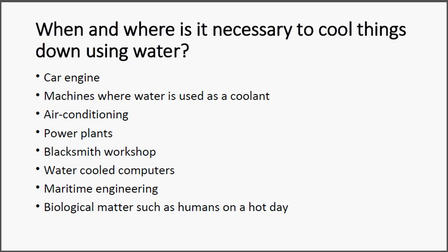And in a car engine, it's a little bit special as well. We don't want it too cold, but we don't want it too hot either. Water has a boiling point at 100 degrees. If we pressurize water, or put water in a pressure system, the temperature can go a little bit higher to reach boiling point, and so we can keep an engine at a comfortable, close to 100 degrees without any problems, in a pressurized cooling system.